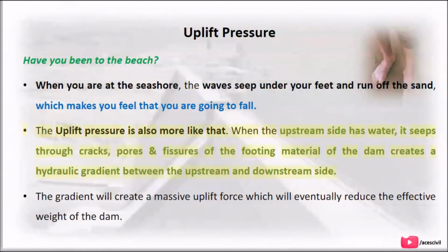When the upstream side has water, it seeps through cracks, pores and fissures of the footing material of the dam, and creates a hydraulic gradient between the upstream and downstream side. The gradient will create a massive uplift force which will eventually reduce the effective weight of the dam.